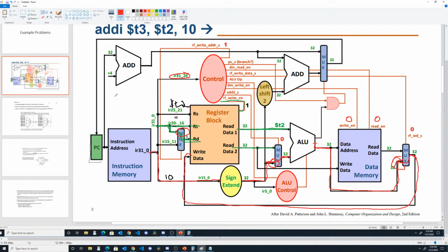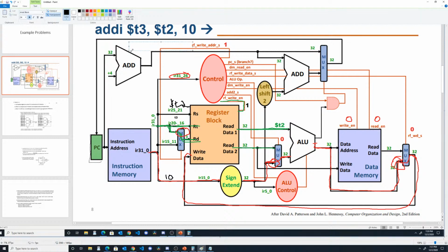So typically, if we're doing some math instruction, if we're not doing a branch, you would just go to the next instruction. And we see right here, this takes the PC counter value and adds 4 to it. So this is the next instruction that's being calculated right here.